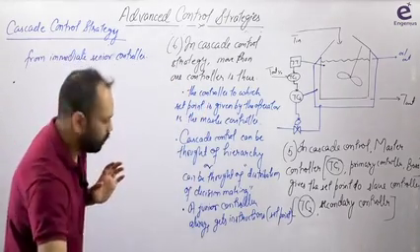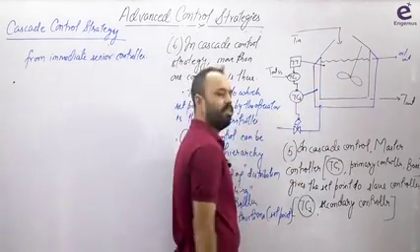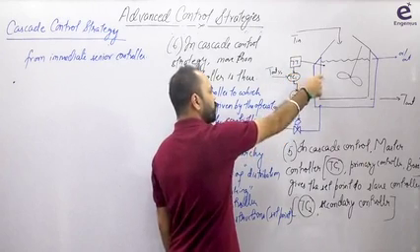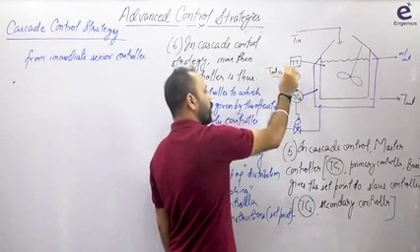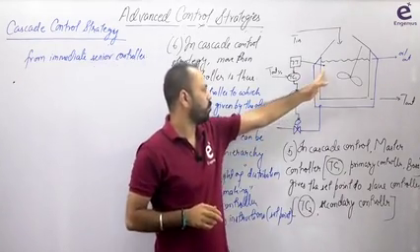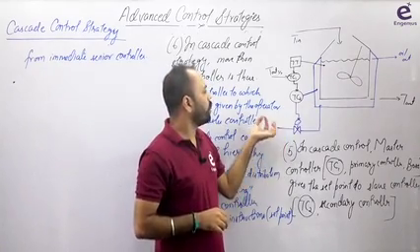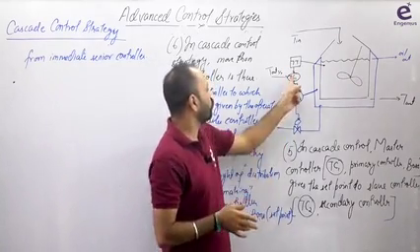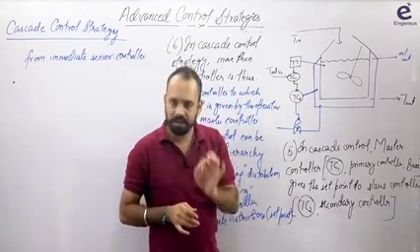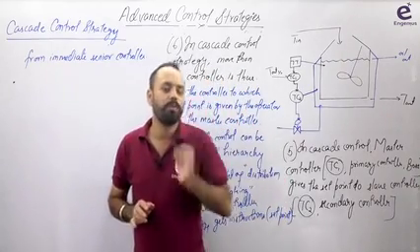Now what happens here? See, now suppose we have to maintain this temperature at 70 degrees Celsius. Temperature transmitter gives TC1 that this temperature is 70 degrees Celsius. TC1 receives the input. Now TC1 is just going to decide that for maintaining this temperature at 70 degrees Celsius, what should be this flow rate. Sorry, correcting myself, this is cascade. This TC1 is just going to decide what should be the jacket temperature. That's it. That is called distribution of decision making.